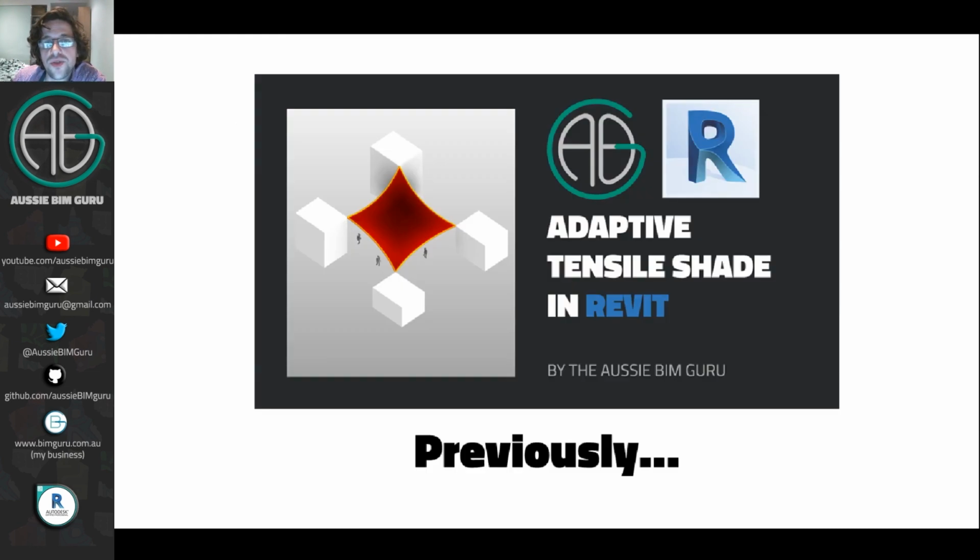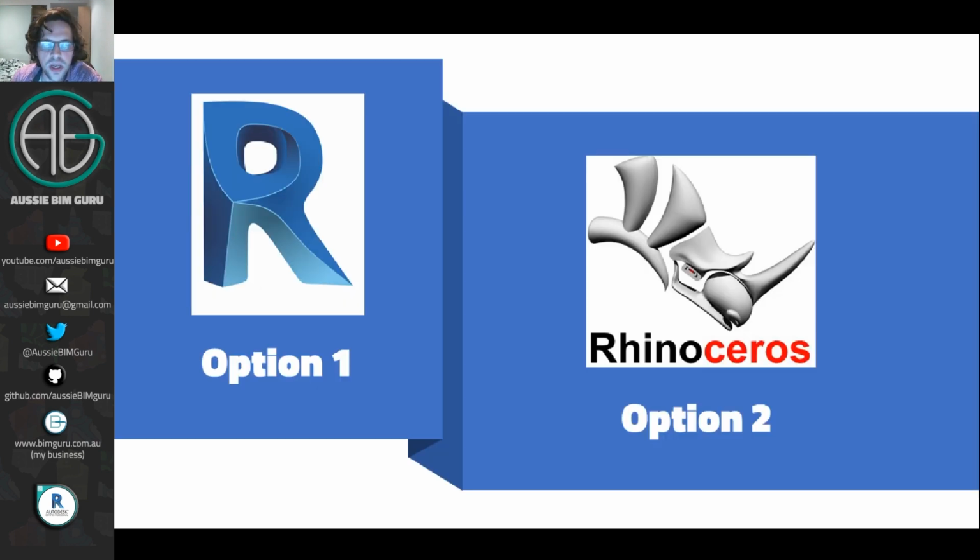So previously we used just purely adaptive components to place such an element, and we just used basic parameters to control the tension and the sag. So whilst this might be semi-accurate in terms of representing tension and sag, it's not really related to a physics-based test, but we can actually introduce some physics to this as well. To do this, we're going to have to use Rhino 3D, or more specifically Rhino Inside.